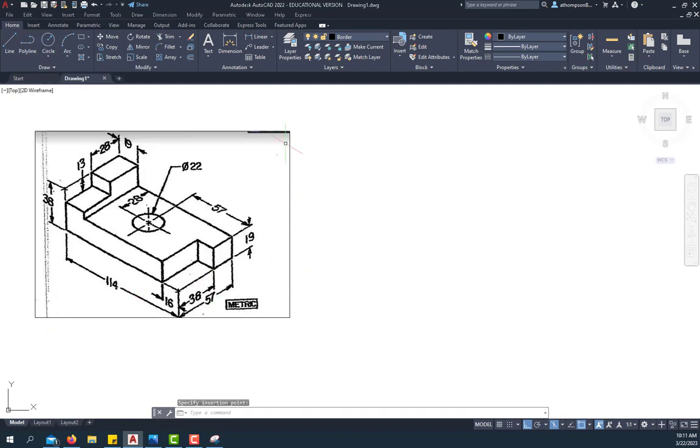You guys don't have to do this because you can see it up on the big screen. But when we're looking at this object, we know, and we've drawn it before, it's 114 back. So you want to make sure your ortho is on, isometric drafting is on, and then O-snap is on.